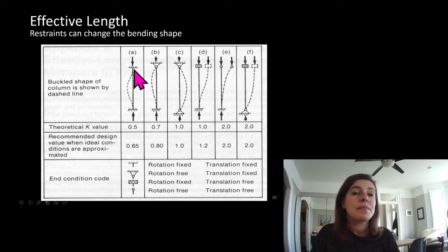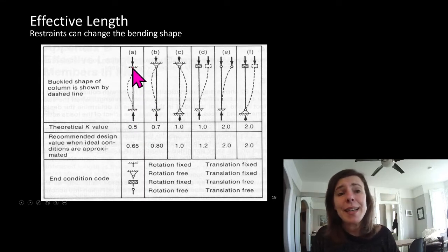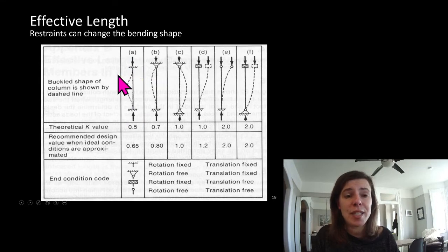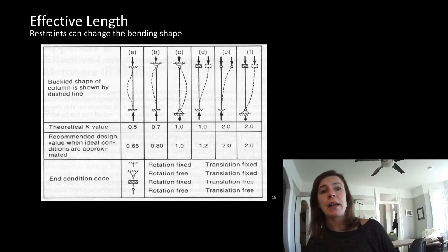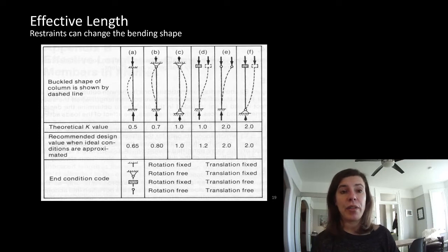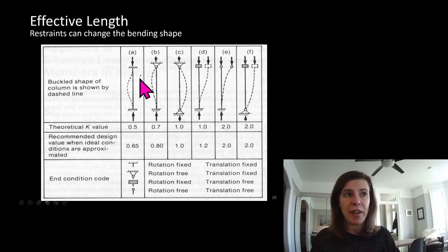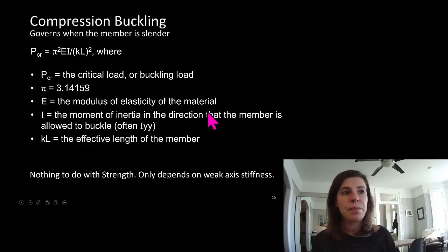Now, you're probably thinking, well, if it shortens our effective length, why don't we do it all the time? Because it comes at a premium. If we've got moment connections here, all of a sudden we have to weld them up and make the moment connections and design them. And last term you guys saw a lecture on the impact of moment connecting all of our things together. That it can work and there can be advantages to it, but we have more material, we have more deflection of overall shapes if we're talking about our lateral load resisting system. So it's still not a thing we do lightly, but if we've done it, we might as well take advantage of it and reduce that effective length.